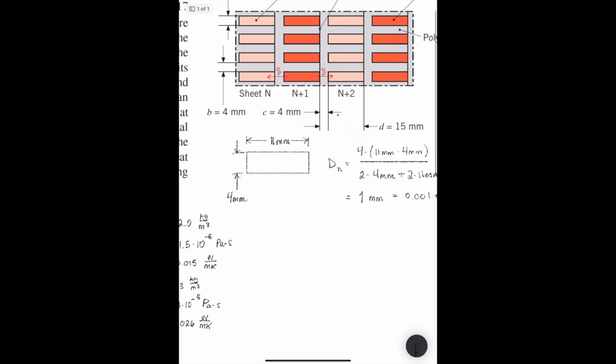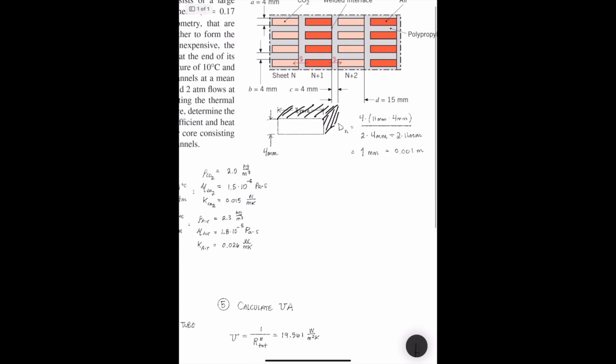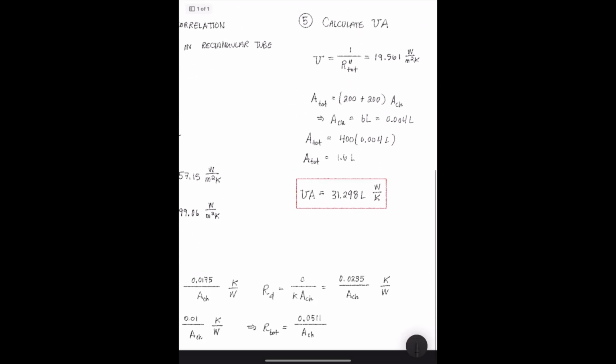The reason we are isolating out this channel area in our resistance solution is because we don't know the total contact area of these channels for the heat transfer to occur. If you can imagine, these channels extend out in 3 dimensions. The heat transfer is occurring on this 3-dimensional surface rather than just on the 2-dimensional one. And since we don't know this full depth into the page, we have to solve this in terms of the area.